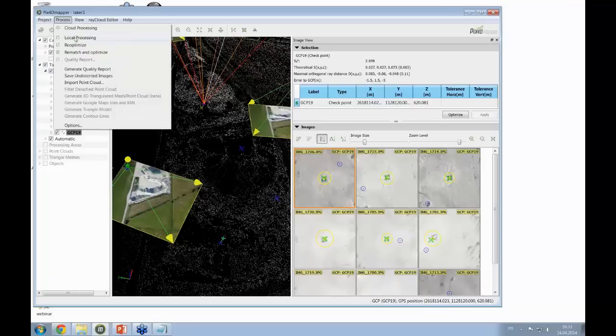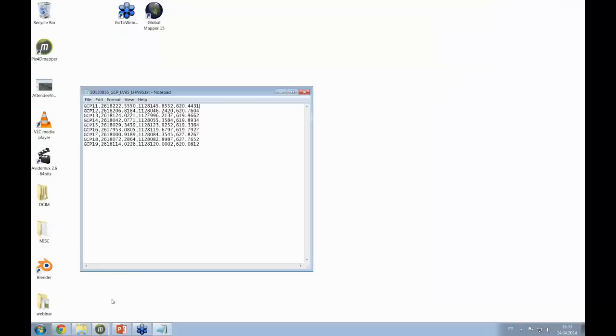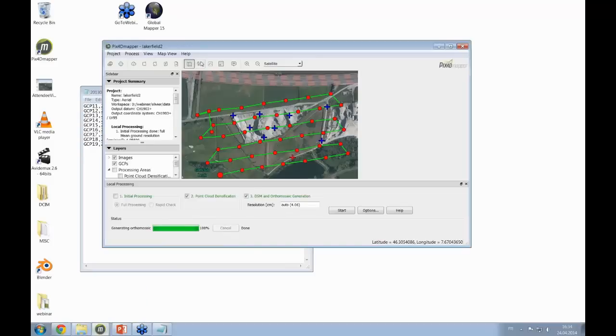including all of that, I'm going to click on Process and Re-Optimize. This is going to be much faster than the first step and will basically take my ground control point information to geolocate and to minimize the error at the ground control point. So just to save time again, this is something I've already done in this project over there.